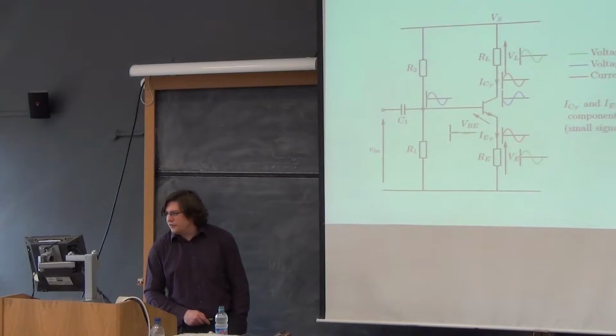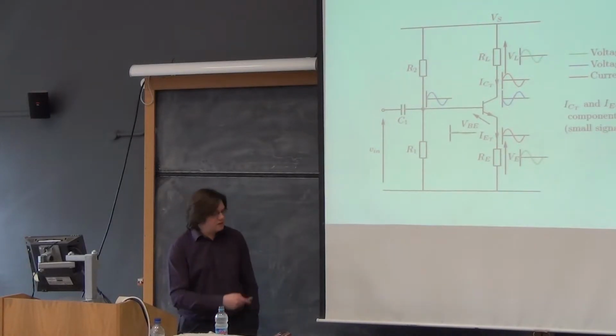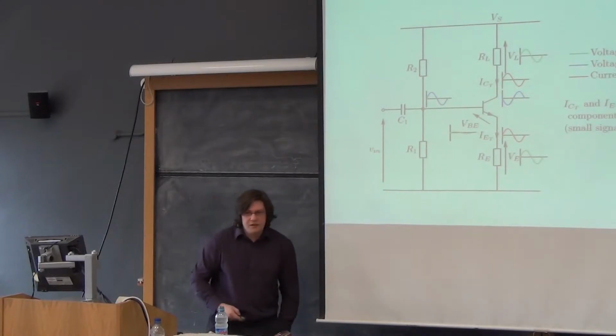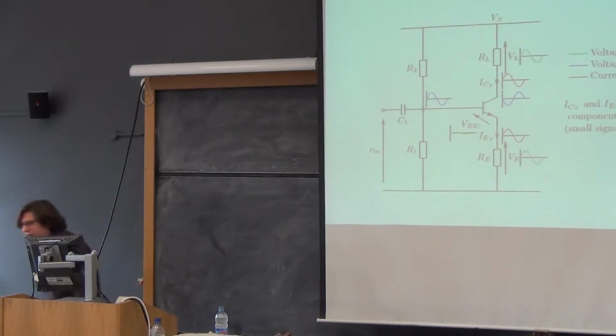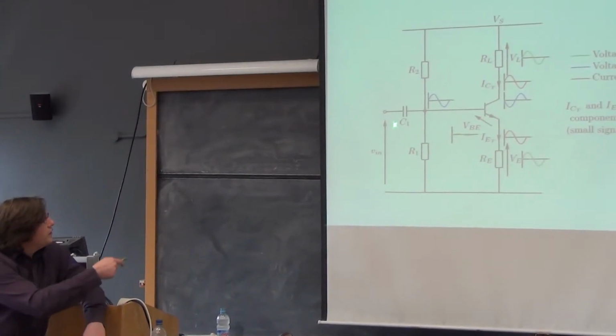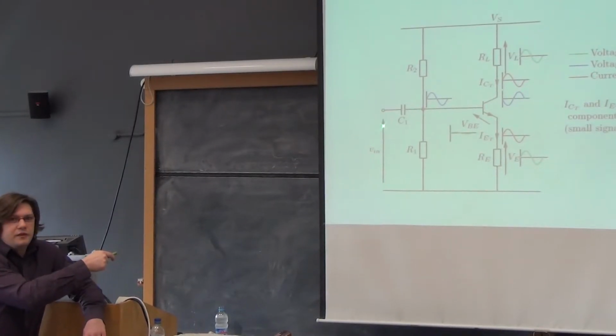So this is the feedback of signals in amplifiers without emitter decoupling. So without decoupling means no capacitor just there. So the order I like to look at this in, which is not the only way, but it's the one that I prefer, is to say there is a voltage on this node which is passed in by virtue of Vin being there, and this voltage perturbs VBE somewhat.